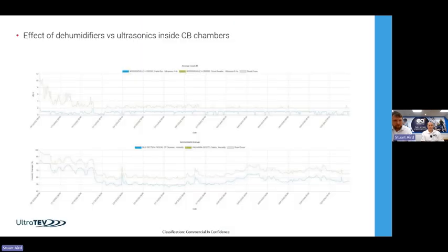With our monitoring system, you can see here that activity was very much related to humidity. So we weren't fixing it by controlling humidity, but in terms of buying time, in terms of slowing the progression, putting dehumidifiers in there and lowering the humidity, it's still not quite getting to a level we'd like. It's still 60 odd, 65%. We want to be close to the 55 probably. But from the 90, 89 to where you're at, that's a significant drop, and a significant drop in the level of activity.